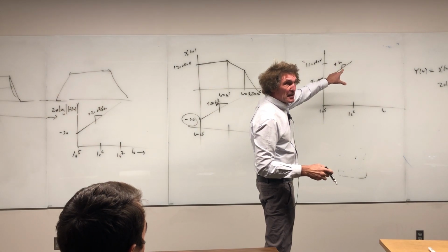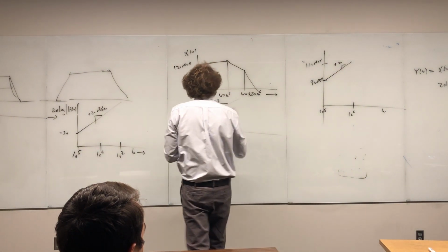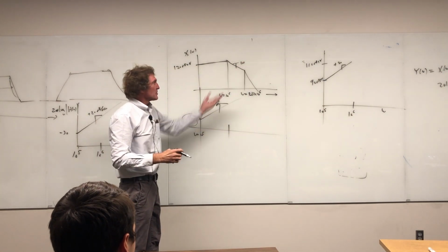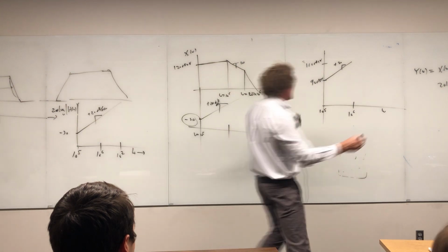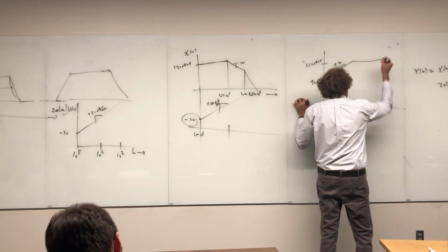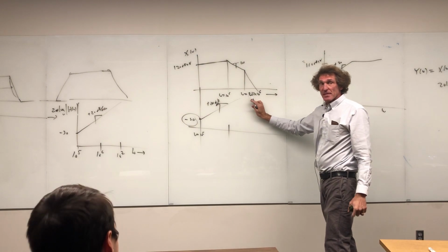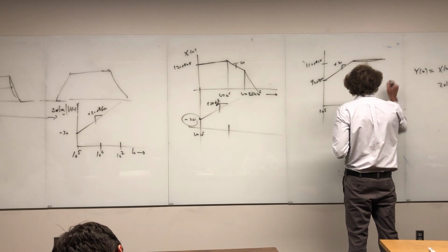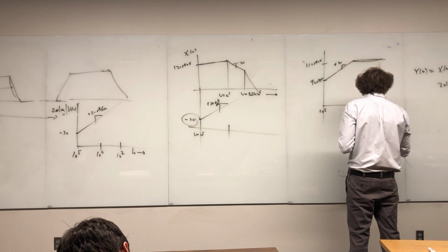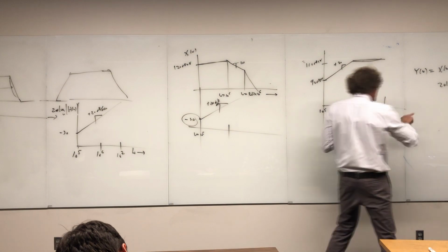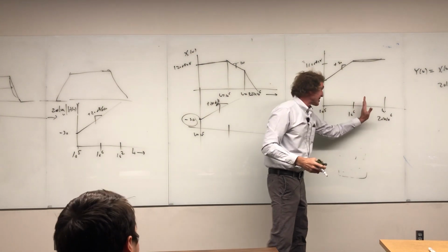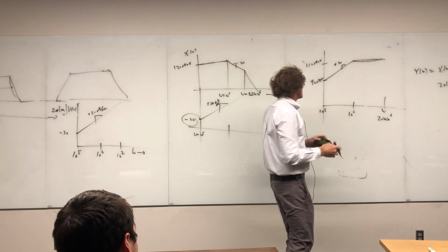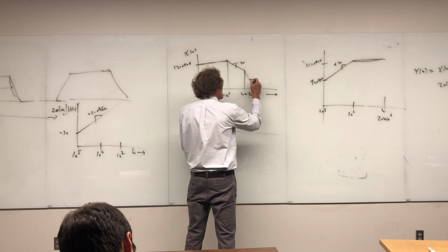Anyway, it goes up to that, right? Now, you'll notice this one starts going down at minus 20 dB per decade. The rate of increase is canceled by this, so it's just flat until it hits this point, 20 times 10 to the 6th. Remember, that's a logarithmic scale, so it's spaced closer to that than you think. And then from here on, it's minus 40.